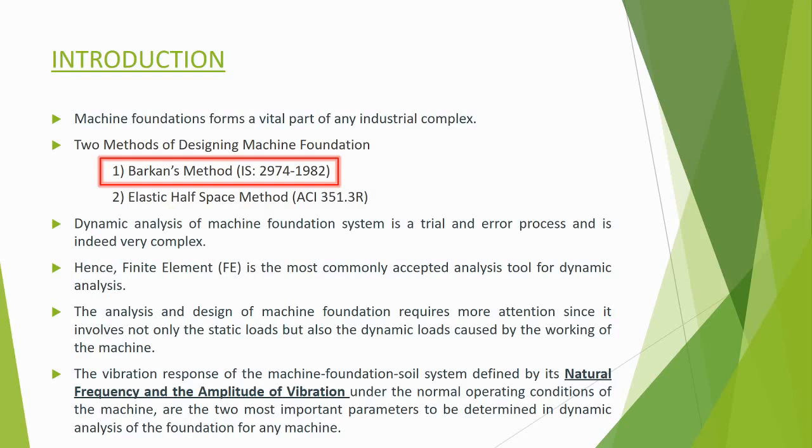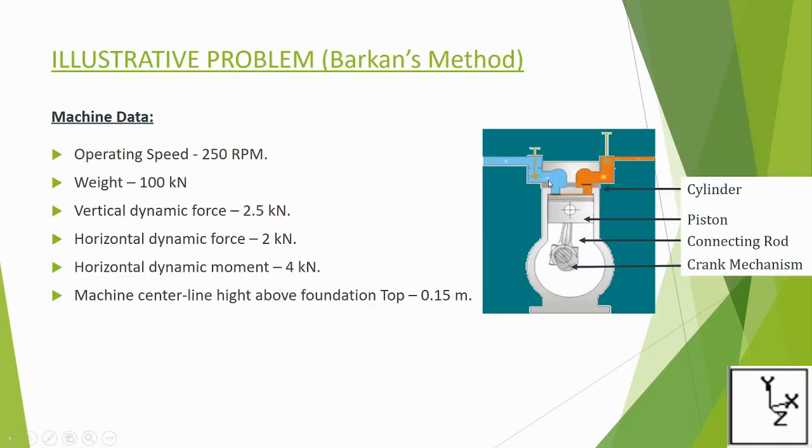The analysis and design of machine foundation requires more attention since it involves not only the static loads but also the dynamic loads caused by the working of machine. The vibration response of the machine foundation soil system is defined by its natural frequency and amplitude of the vibration. So in this video, I am going to show the modeling of machine foundation by finite element method in STAAD Pro software, and after analysis we are going to determine the natural frequency and amplitude of the foundation.